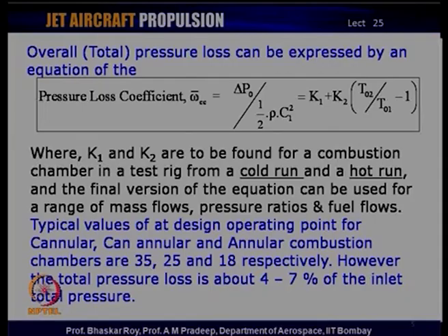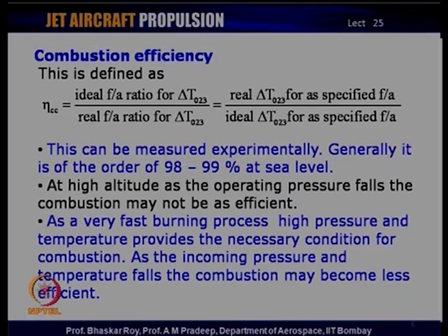The next parameter that we would probably like to look at is the combustion efficiency. Now, the total pressure loss that we talked about, really speaking, has nothing to do with the combustion efficiency, as opposed to all the other components that you may have studied before, where the pressure losses directly impacted the efficiency of those components, notably the compressors and the turbines.